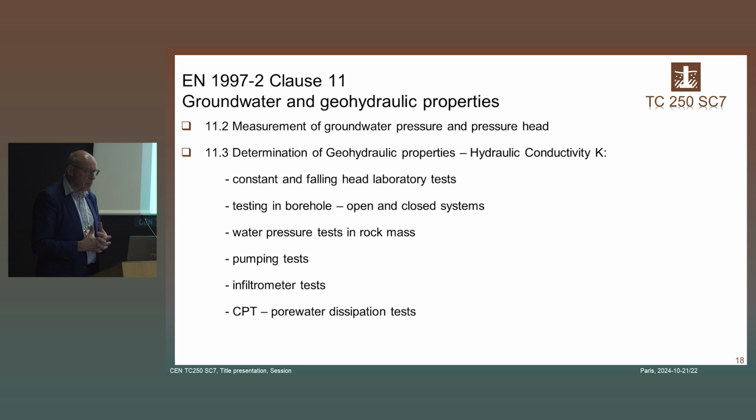And it determines the geohydraulic properties, especially the hydraulic conductivity, on lab tests, constant head and falling head, pipes in boreholes, so standpipes, open and closed standpipes, water pressure tests in rock mass, pump tests, which is a very important parameter, of course.